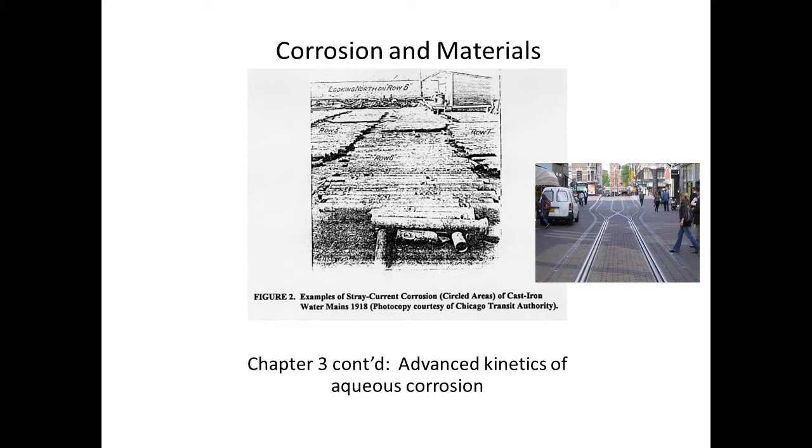In reality, there is some electrical resistance along the sections of rail, and this particularly comes about because the adjacent sections of rail might not be very well electrically bonded, say by soldering, in which case the substation is pulling DC return current, but not all of it is necessarily coming through the rails because the rails are not resistanceless. Instead, a proportion of the DC current pulled backwards into the substation might be drawn from other places than directly along the track.